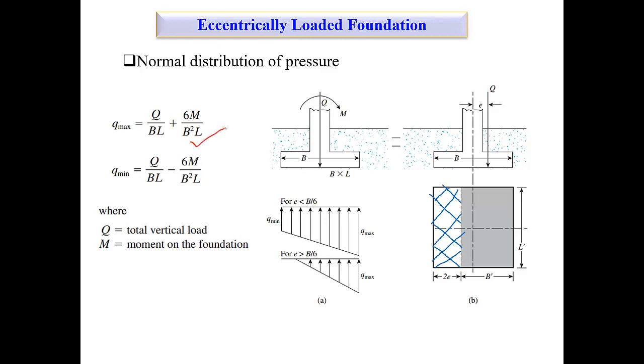Sir, few of us didn't get the point. What is the Kern? The Kern section is the diamond shape, where if you displace your load onto this line or inside this section, your footing will not have any tension.